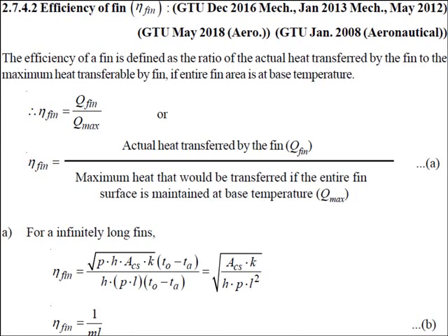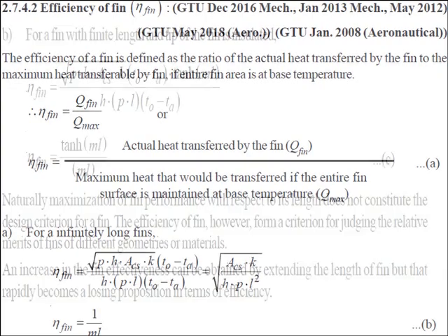So efficiency of fin for the first case is equal to 1 upon ml, where m is the fin constant and l is the length of the fin.